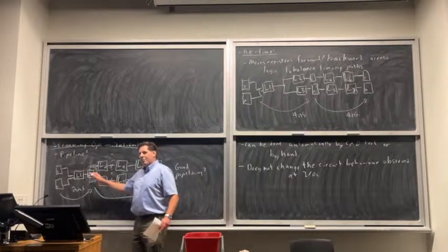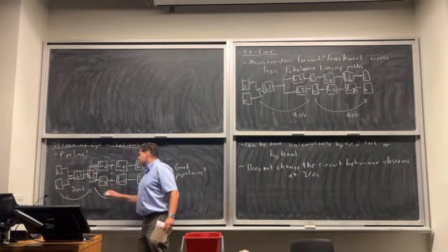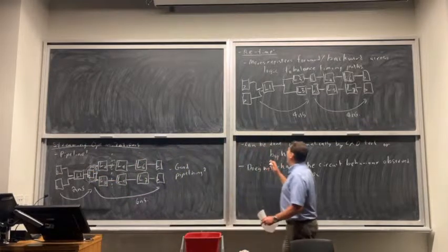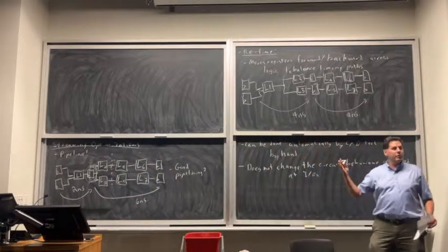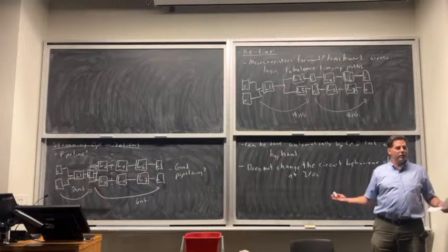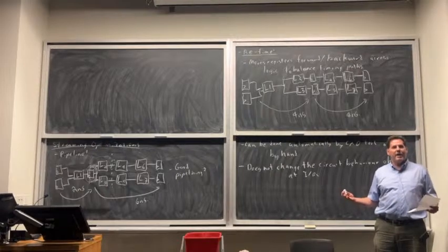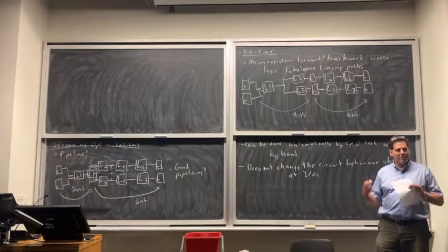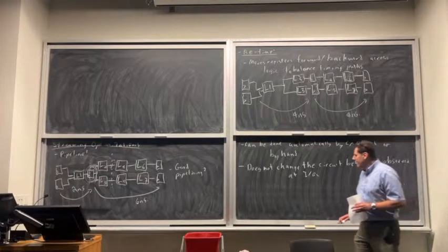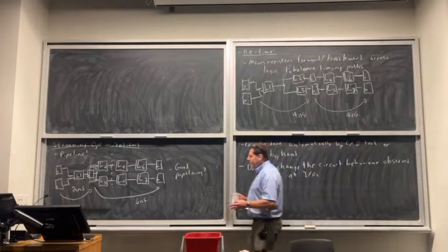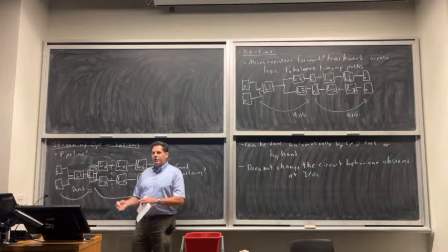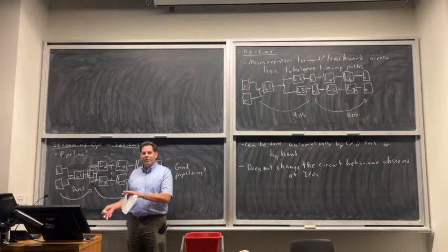If you've used retiming, it's going to be a lot harder for you to interpret what these registers are. These registers are not things that I actually put in my RTL. Does that make sense? But most debugging occurs when you're at the functional level, when you're debugging your RTL, and this retiming doesn't happen for that. This is when it's actually implemented on the chip.